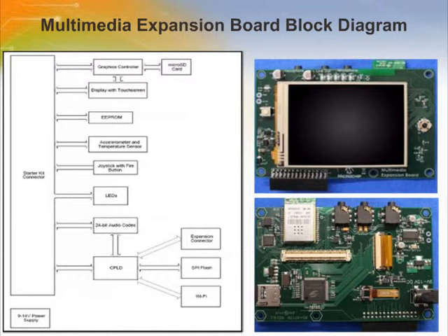It also has an accelerometer and temperature sensor, BMA150, and a 24LC08 EEPROM, a 2 MB SPI flash, which is an SST25VF016, a 24-bit stereo audio codec, which is a WM8731, a CPLD for SPI and chip select configuration, PIC32 starter kit connector, and integrated 802.11 wireless connectivity.